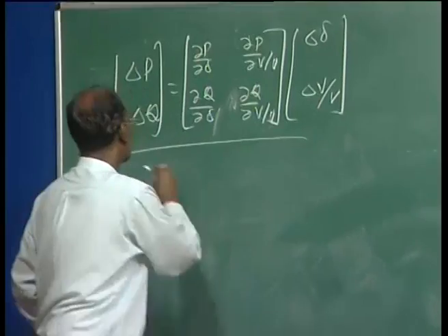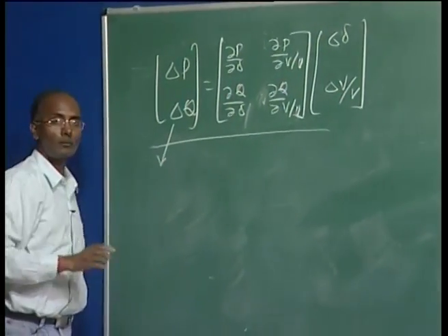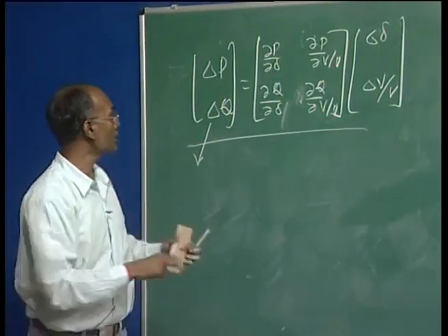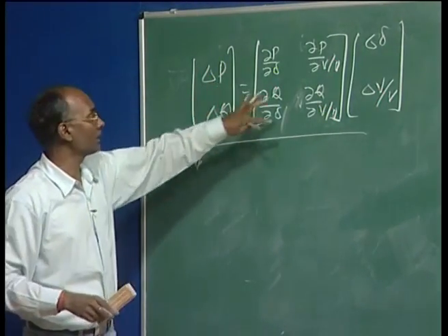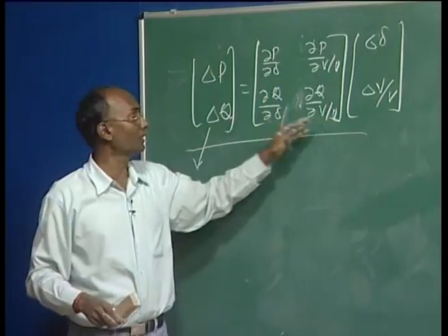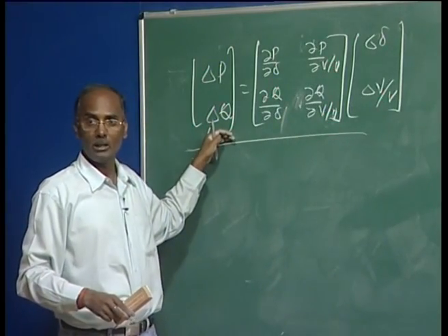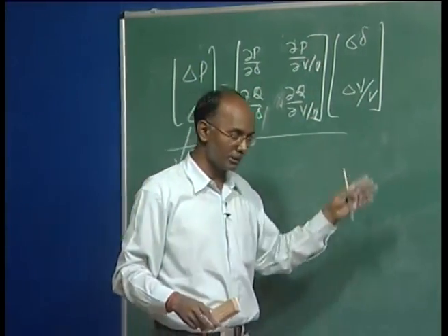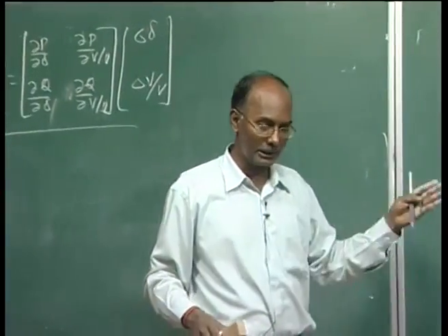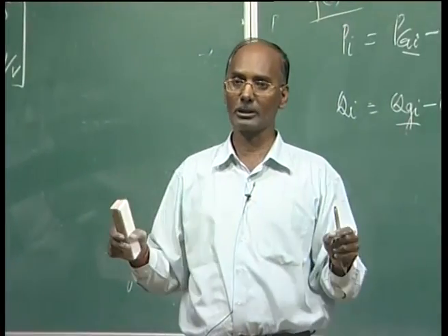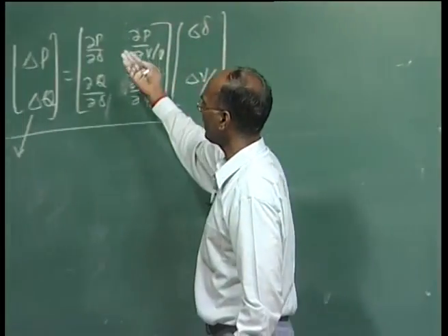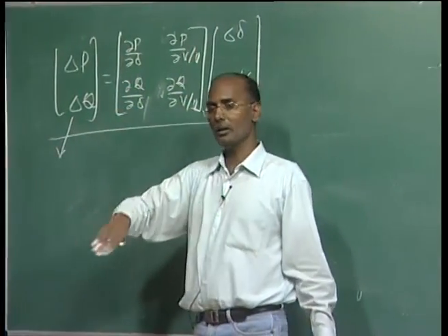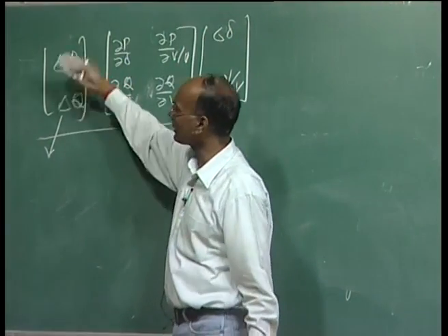Here this Q is basically done only for the load buses, and this P we calculate for all the buses except the slack bus, and then its order is decided by the number of your load buses. Because in the load flow, sometimes the reactive power is hitting the reactive power limits of the generators. If they are violating, then it is converted from PV to PQ, and if it is not hitting, then it goes back.